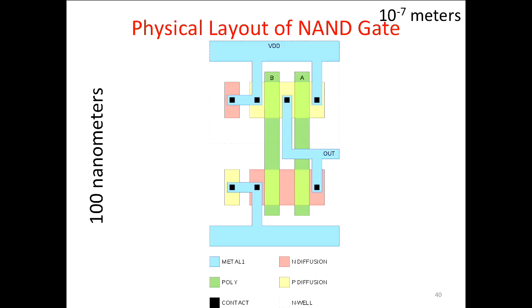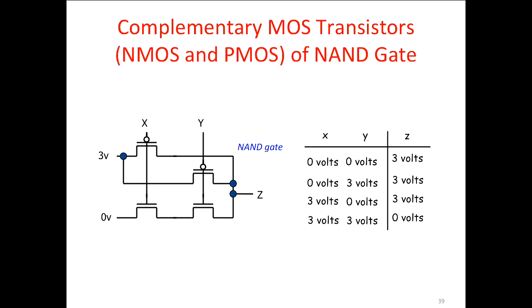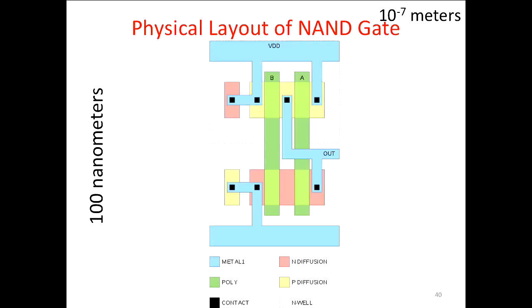And they do other kinds of tricks to reduce the capacitances, like this trick about this node, which is here, between these 2 transistors. They actually share that between these 2 guys to reduce all the capacitance on this output node, right, to save power. So there's a lot of details in this physical design. There are expert designers who spend their lives looking at screens and packing this stuff very tightly.